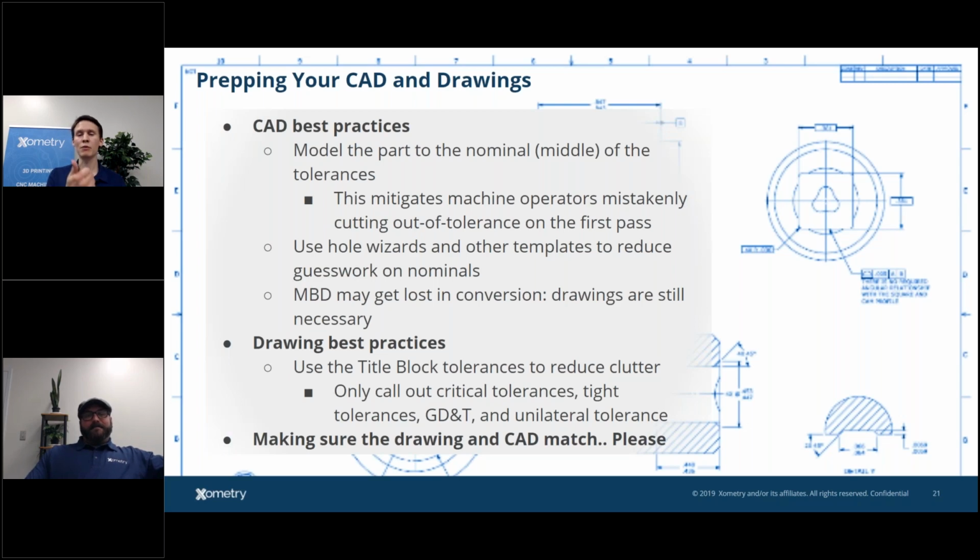Yeah. So the things that we catch that are usually the mistakes are when a hole for a tap feature is too large. We can always make holes larger, but we can't make them smaller. So if you have the maximum tap condition in your feature set, if we drill that out and we don't catch that, then a tap's just running loosely inside. It's not going to be cutting any metal. So always use, I use hole wizards religiously. So those take the risk out of it. But making the feature to the minimum hole tap condition. Always to the minor diameter.